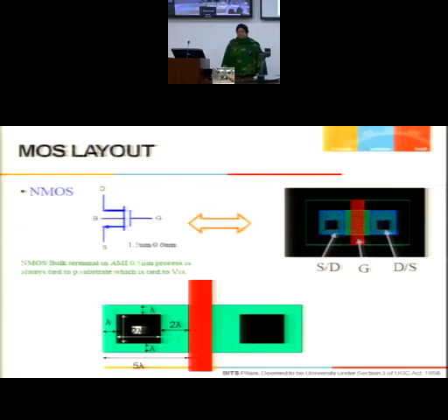Plus the side wall capacitance. How much is the side wall? That's the perimeter. How much will be the perimeter? 2L plus W. We are neglecting the capacitance facing the channel region. So this gives you how much perimeter? 110 lambda into Cj side wall. Clear? You have two capacitances, Cj area and Cj side wall. Is this clear? I hope you all understand what we mean by side wall capacitances and area capacitances. You have learned about them.